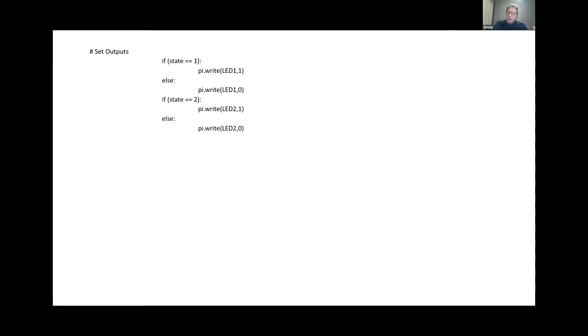And I'll start doing things like this time around the loop, update this part of the screen. So when it gets to 500, the next time around the loop, it gets to 501, I do another part of the screen. And I separate out the workload for the non-critical functions.